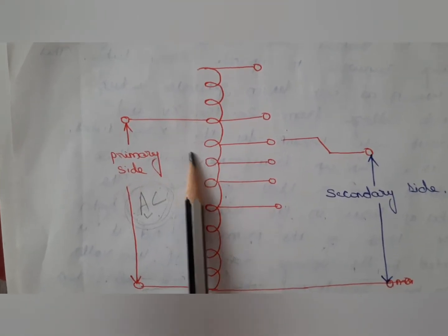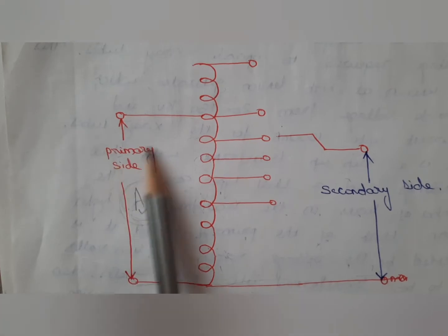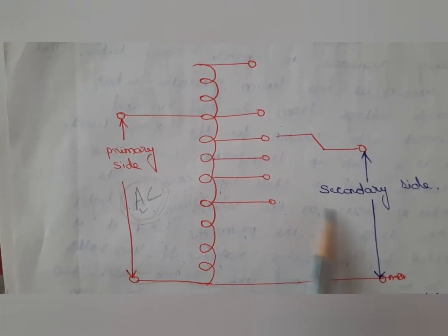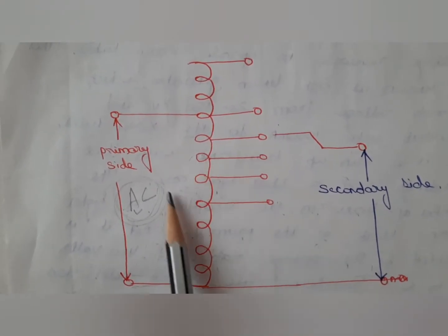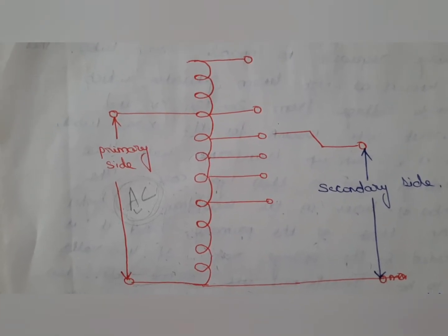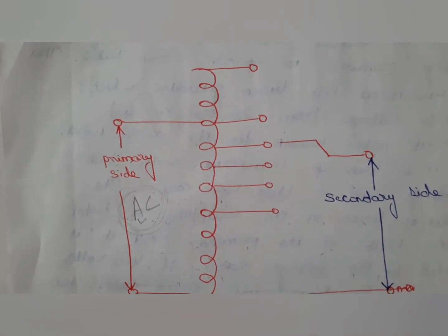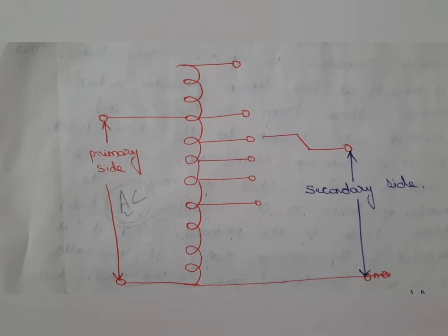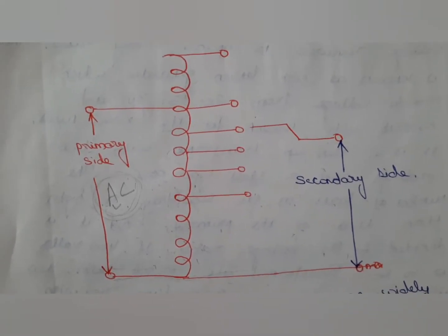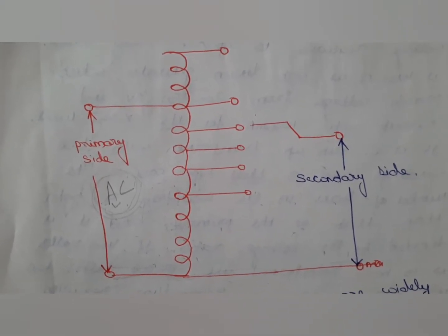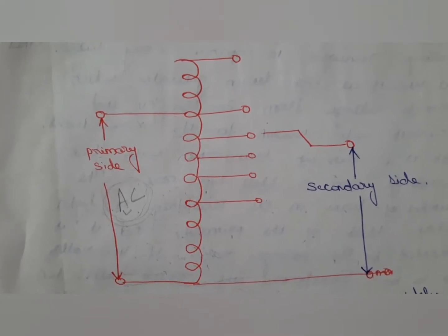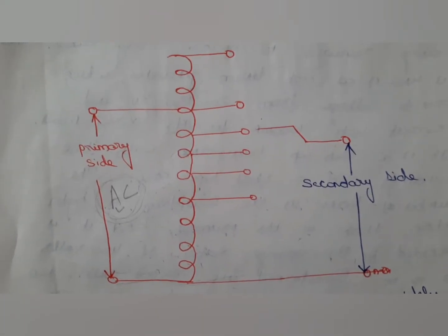And also there is no electrical insulation between the primary coil and the secondary coil. So these autotransformers are used in the X-ray generator circuit in order to adjust the voltage applied to the primary of the high voltage transformer.